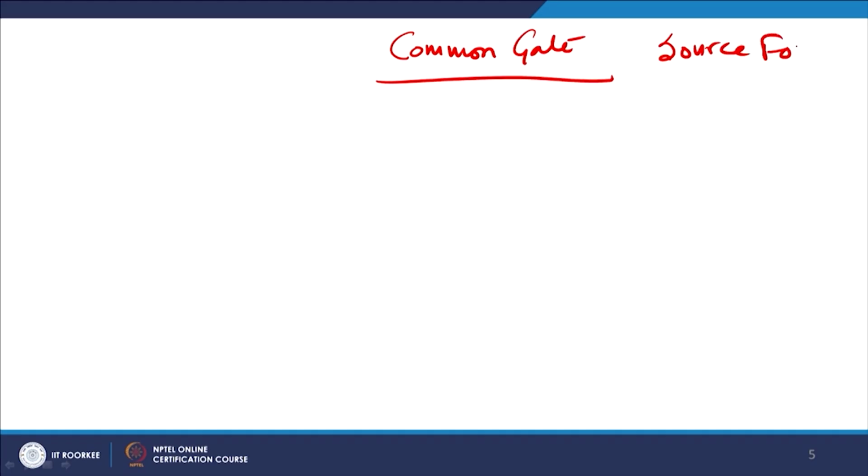This is what we get from our previous discussion and knowledge as far as this design is concerned. We have also understood the basic concept. Let me come to the next one, which is basically the common gate design. The gate is grounded, and therefore I will do the common gate design. It is not seldom used; it is also known as a source follower design, which means that it is a follower, and its gain is almost equal to 1.